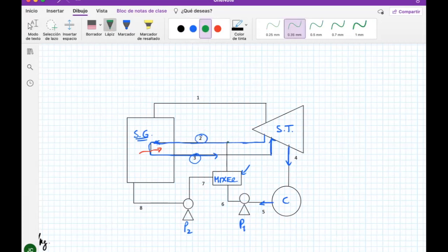So far it's the same thing as a typical Rankine cycle, but I have also introduced another improvement, and this is called the regeneration, okay? The regeneration means that I'm gonna use a certain amount of steam, not the whole deal, but a certain amount of steam that I will call Y. And in this case, Y equals to M from the mixer, divided by M1, okay?